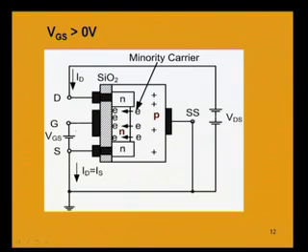So, basically, when we have a VGS positive, we have an abundance of electrons, because the positive terminal of VGS is attracting minority carriers from the p substrate, and these minority carriers take part in knocking out more electrons because their kinetic energy is increased by the application of the gate to source positive voltage. So, we have a greater drain to source current. So, there is enhancement in the current flow.